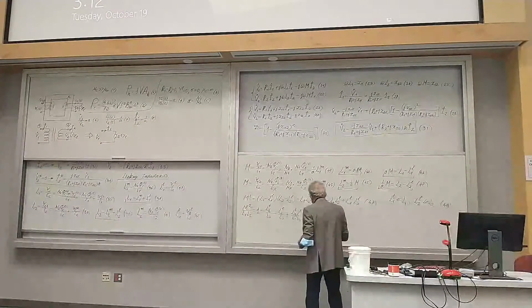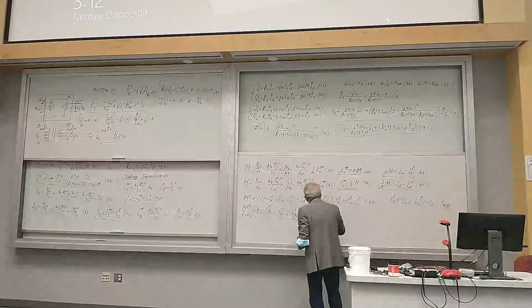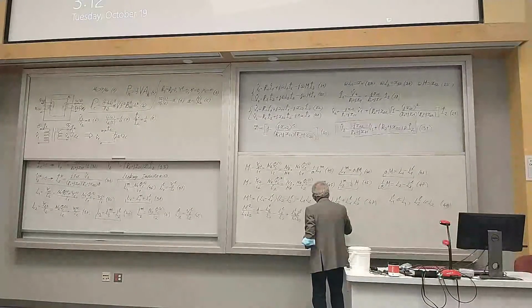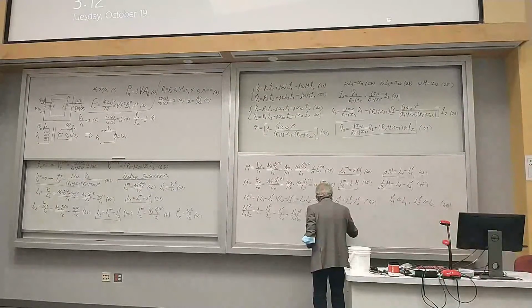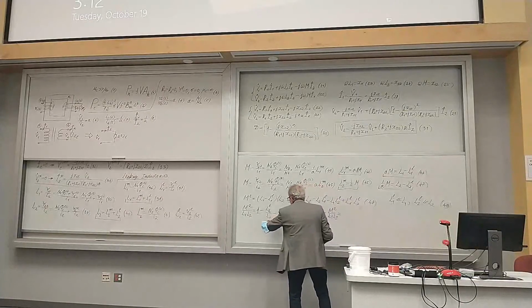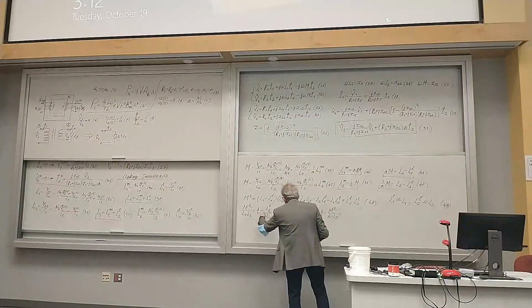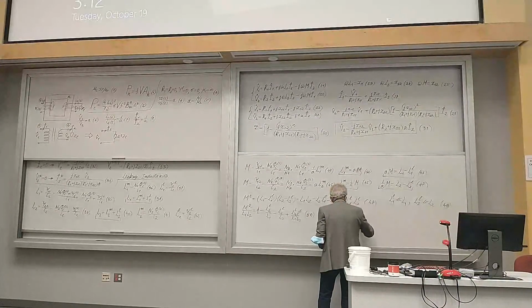So then you will write from here, neglecting it, that 1 minus M squared over L sub 1 times L sub 2 will be determined only by the leakage inductances. So what I did, I moved this term over there and I moved it here. And it will be L sub 1 leakage divided by L sub 1 plus L sub 2 leakage divided by L sub 2.